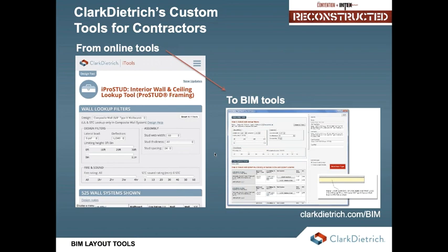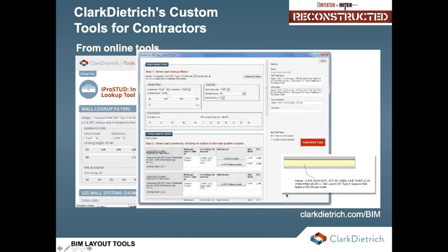So for architects, they've got to have wall types like you see right here on the very bottom right. These wall types really are nothing but information. The wall types hold information of what's in the wall, what kind of insulation you have in there, how many sheets, layers of drywall you have on there, what type of stud, spacing, and all that. So it puts it all together as information, basically. That's the I for BIM.